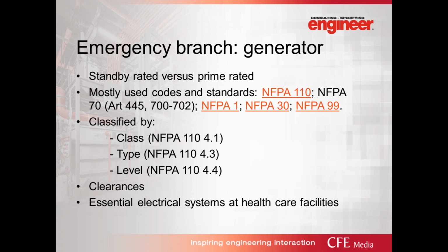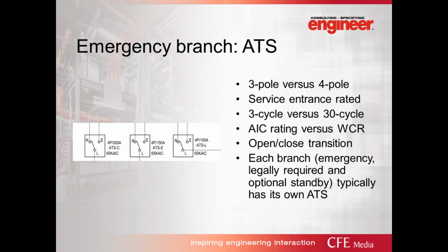The critical branch is more straightforward than life safety. The intent is to provide a power for direct patient care. And the final choice for the essential system is equipment branch power. This is where the medical gas equipment or other medical systems can reside. The system such as operating rooms HVAC, heating for patient rooms, or cooling for data rooms can be placed on a delayed equipment branch power.